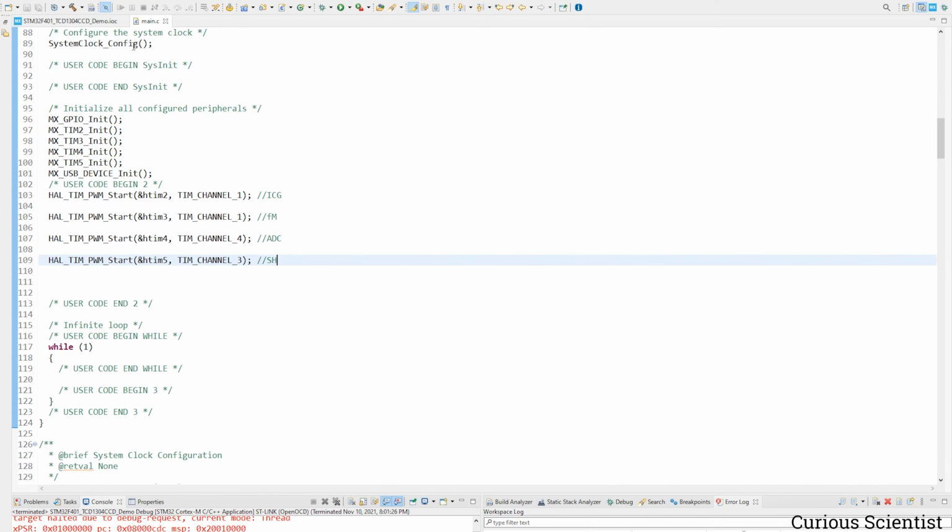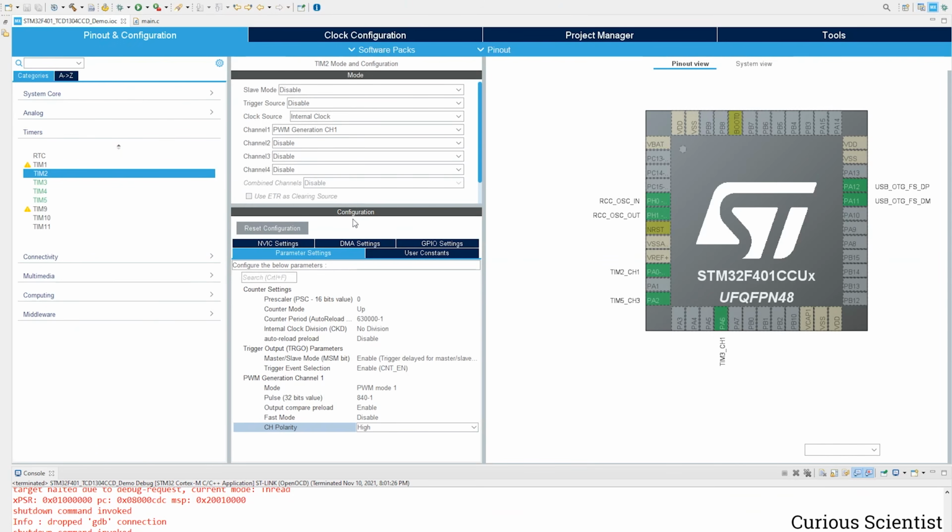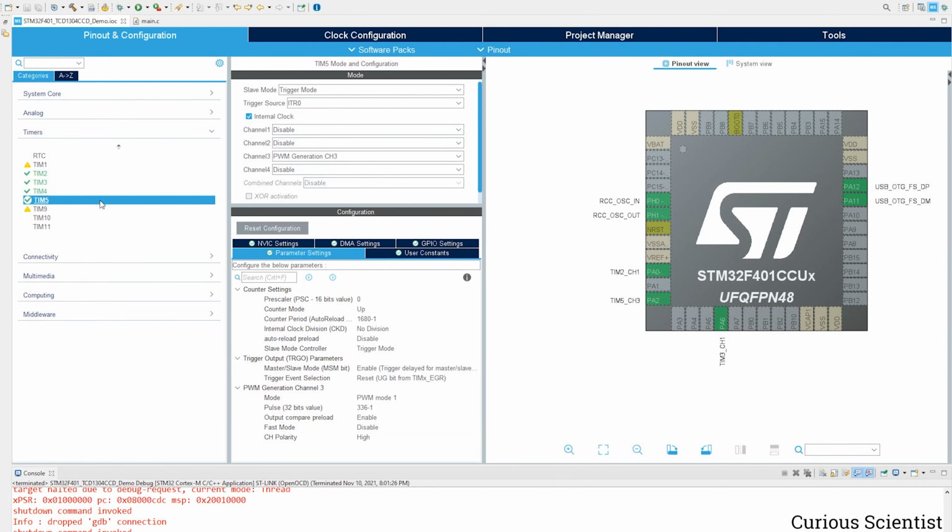And how you can do that is you go back to the configuration, and you go to the corresponding timer, which will be timer 2 and timer 5, and you make sure that you generate the proper cycles. There are just 2 timers and 2 different options, so you can have 4 different combinations, so you can figure it out quickly if you don't have an oscilloscope, for example. So everything is fine, but we have to add the delay.